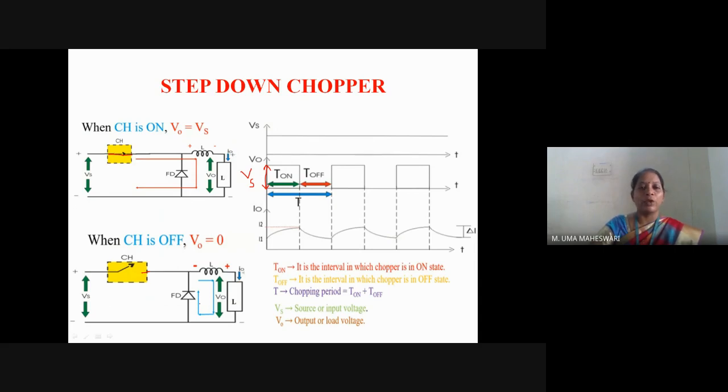So in this circuit, what is happening? How is the power flowing during the off period of the switch? Here you can see that whatever energy is stored in the inductance is freewheeling through the short circuit path. Because of the polarity of the inductance, minus connected to this freewheeling diode cathode, and positive connected to this freewheeling diode anode, the freewheeling diode gets forward biased.